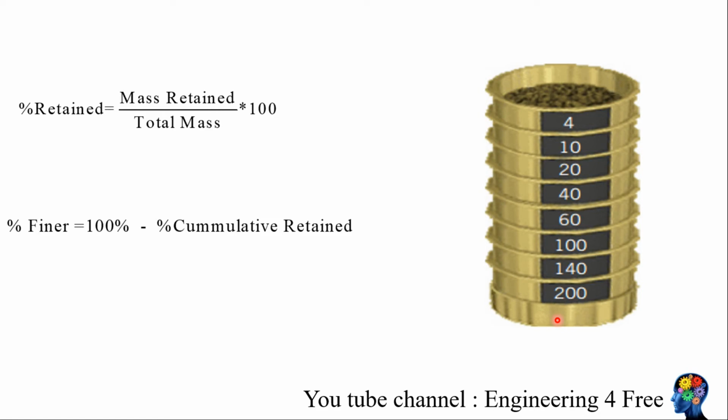When you want to calculate the particle size distribution curve, you have to calculate the percentage retained and percentage finer. Percentage retained is mass retained on that particular sieve divided by total mass multiplied by 100, whereas percentage finer is 100% minus percentage cumulative retained.